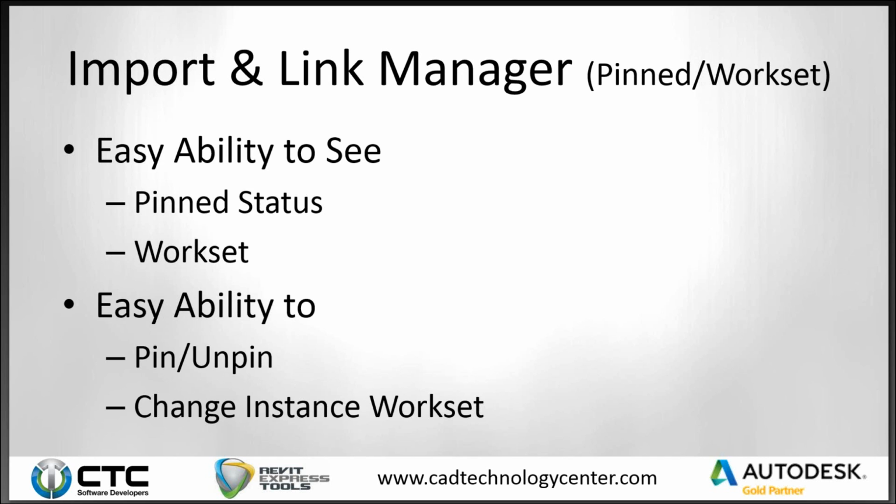We're also going to go through the main interface a little bit and take a look at pin status and work set of linked Revit models. You're going to see the ability to unpin or pin something and change the instance work set specifically, the instance work set, not the type work set. We'll take a look at type work sets a little bit later on.